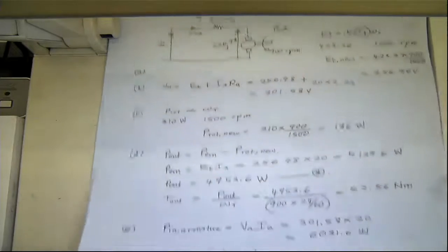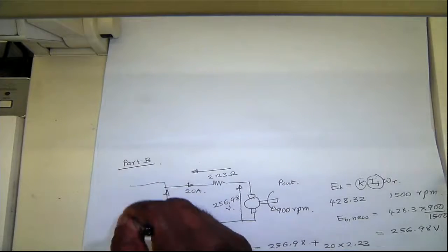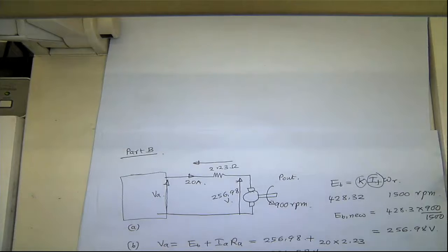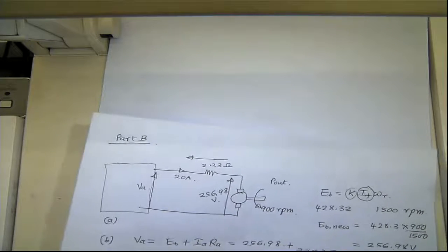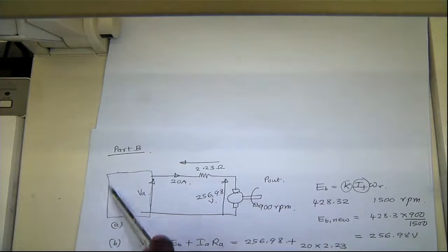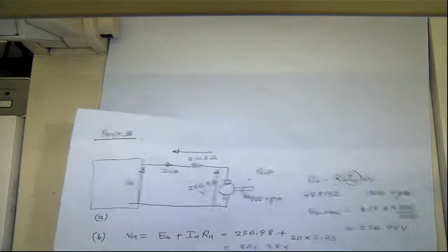Modern DC motors have some kind of voltage regulated supply, which can give low voltage when it's starting and then ramp up the voltage. But if there's no point in having a voltage regulated supply, then the crude method is to have series resistances.